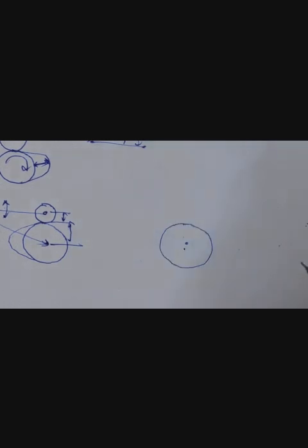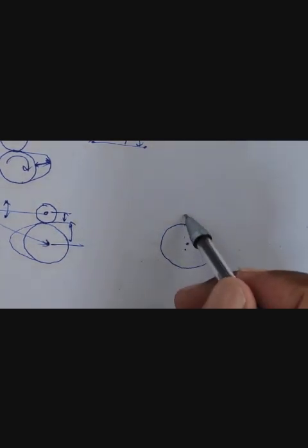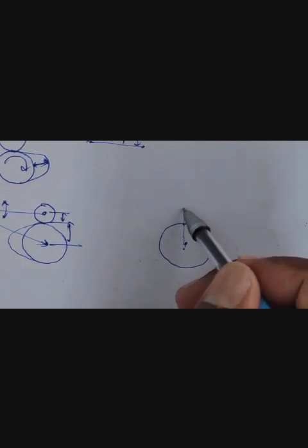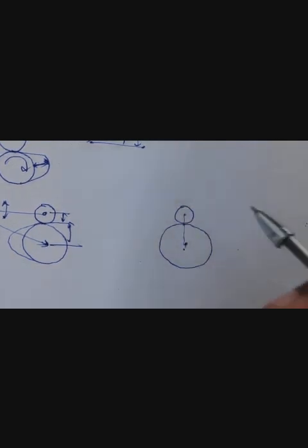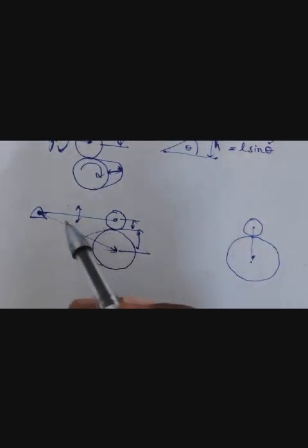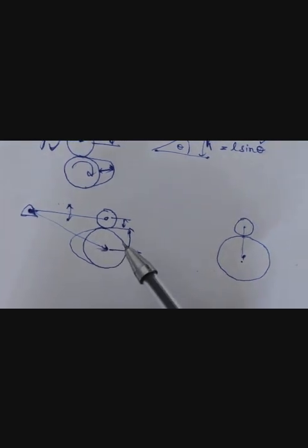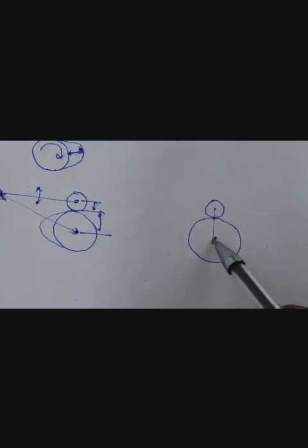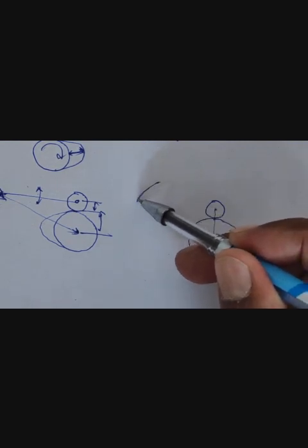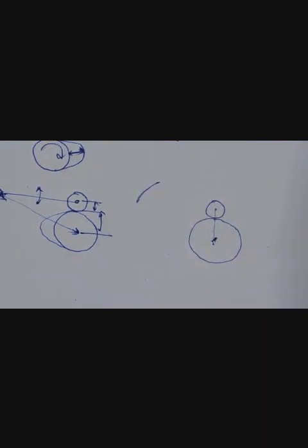The center of the base circle is this, and then draw a vertical line, and again draw a roller with the specified roller radius. Since you know the distance between the pivot point and the base circle center, you measure that distance with the compass and cut an arc.